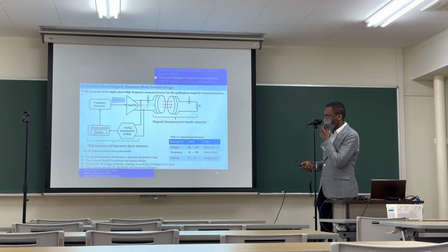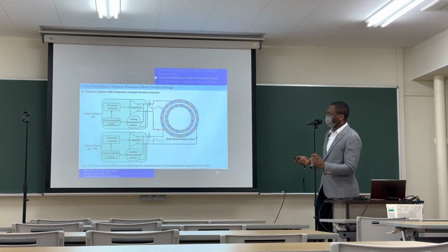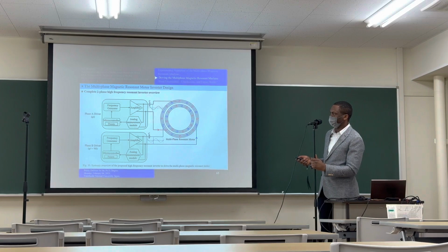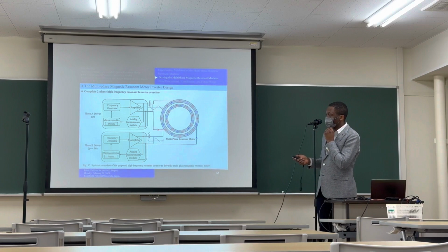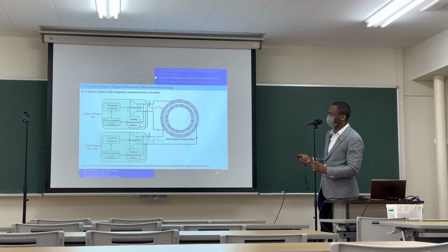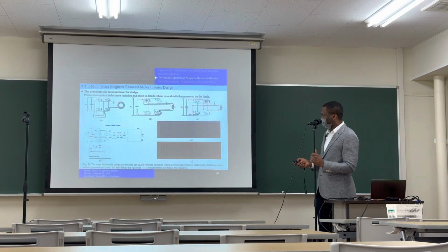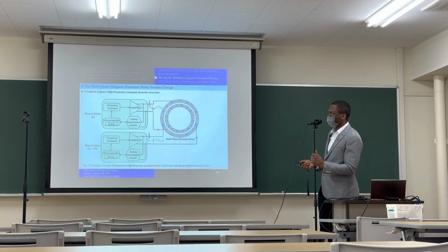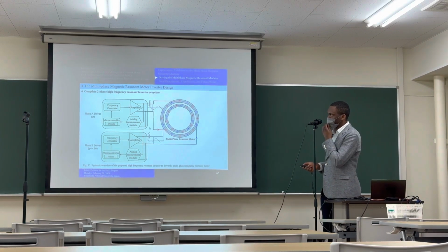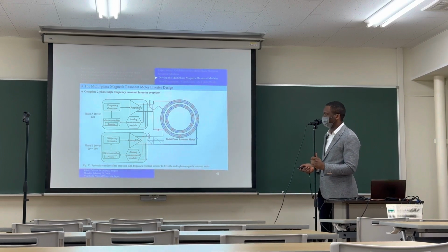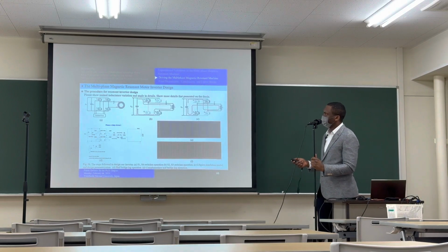So we're going to use a microcontroller. If we design one of it and make it modular, we can use two of them, because for running this machine, since we have two phase coils, we need two of these inverters. So we just focus on designing one, and then we use two of the design to run the machine. That is the main idea. And the microcontroller produces two waves, the voltages for the two coils, that are going to be 90 degrees out of phase. And then we engage in the design.